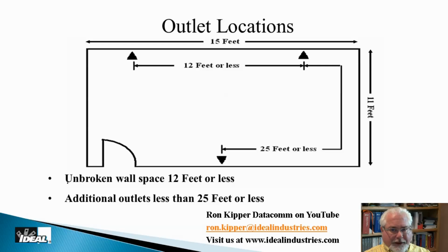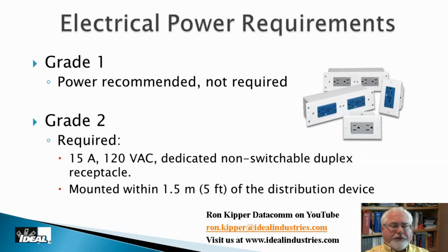We're not daisy chaining wires in any way, shape, or form anymore. Some contractors might refer to it as star wiring, where we come from a central point like our low voltage panel, and we wire to each individual outlet separately. And no splices can be happening in those runs. If you cut the wire accidentally or during the installation, technically we're going to ask you to pull new wire. So no splices in any of those home runs out to the outlets in the rooms.